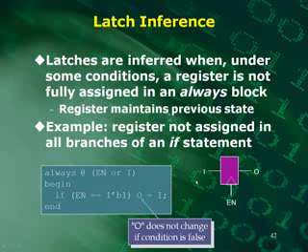Now your tool will tell you if you've inferred latches, and you need to look at that very carefully and determine what you were really trying to do. Were you trying to create a flip-flop, or were you trying to produce combinational latches? Do you really want a latch?